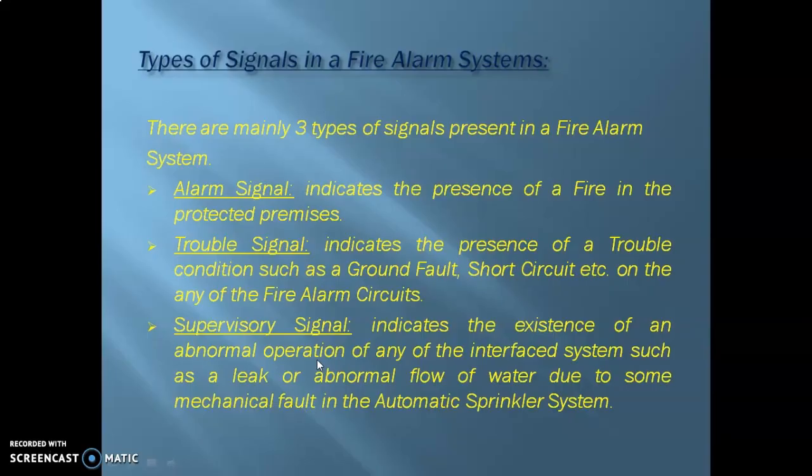Now, this fire alarm can be detected using any of the initiating devices like the manual pull station, the smoke detectors or heat detectors, or even the sprinklers that behave as heat detectors, since the fire alarm system is actually interconnected to the sprinkler system.